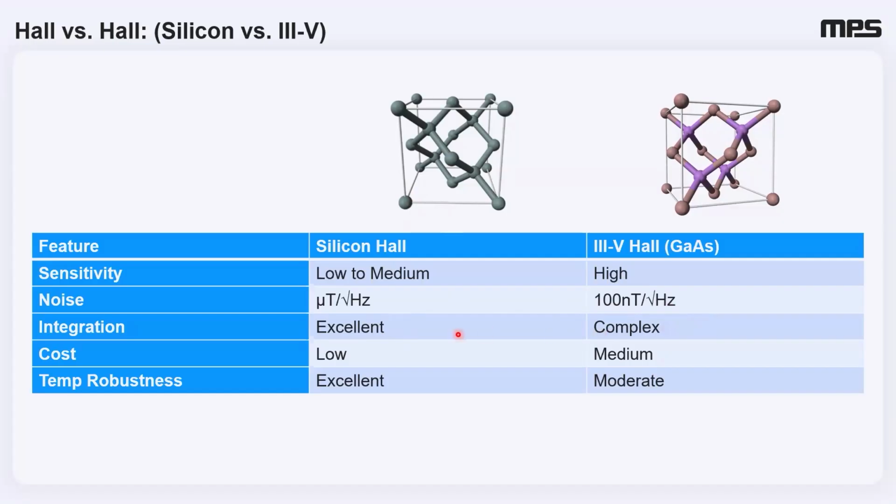And so what happens in practice is you've got your silicon with all your FETs and resistors and everything, and then you take a second die and build your Hall devices, and then you connect. So these are almost always going to be dual die devices at least.